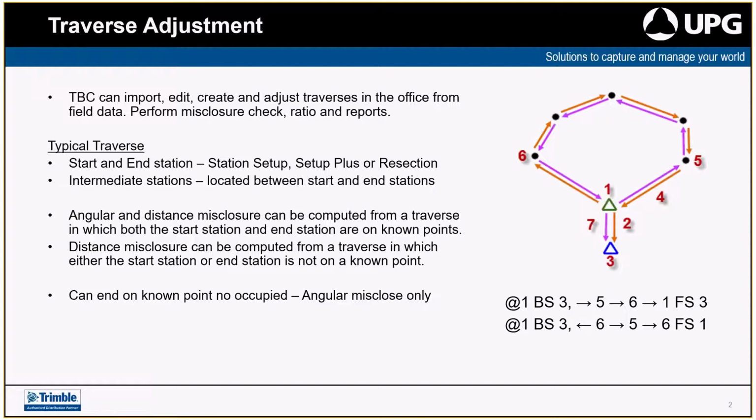But ideally, we really like to keep it as the conventional Traverse. It makes it nice and easy for everybody, and it's better for the program to be able to calculate everything you want. You can obviously change up your Traverse and set up on 1, backsight 3, sight 6 and 5, so turn all 3 at once, and then traverse through, finish on 6, backsight to 1, and have that as your closing line. But ideally, you'd want to have a closing line.